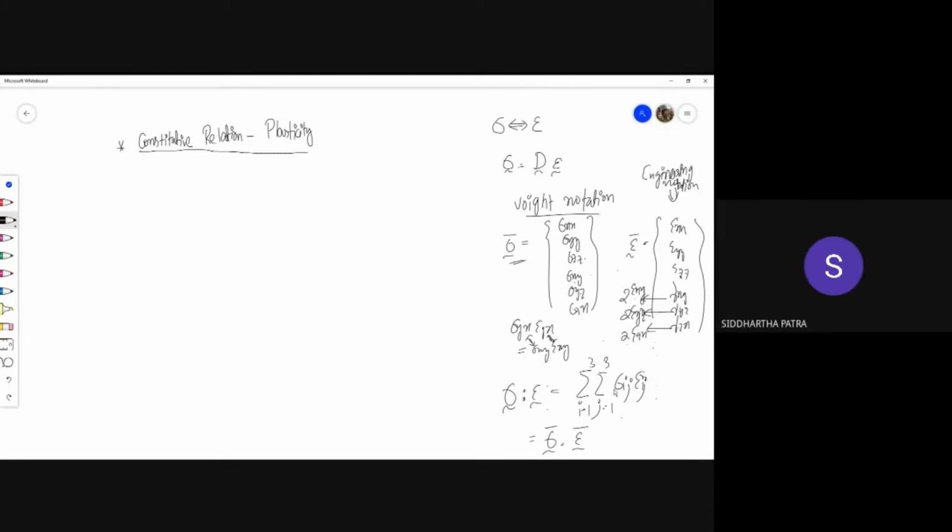One more thing you might notice, that I'm taking inner product of two matrices and inner product of two vectors. Okay, sigma and sigma bar is different. So sigma would be this quantity. Sigma would be like sigma xx, sigma yy, sigma zz. Okay, sigma xy, sigma xz, sigma yz. Okay, and so on. Okay, it's a symmetric matrix. So this multiplying the strain matrix, okay, as I explained, using term by term multiplication, and the same thing can be achieved by taking dot product of these two vectors.